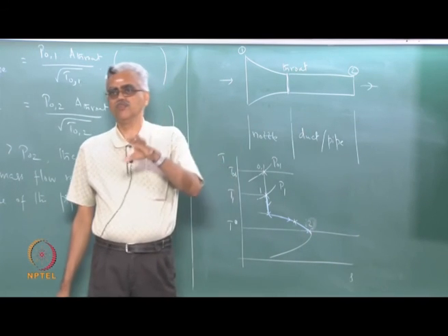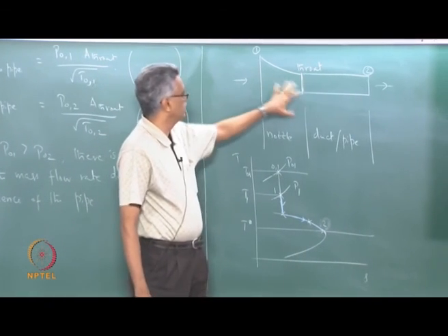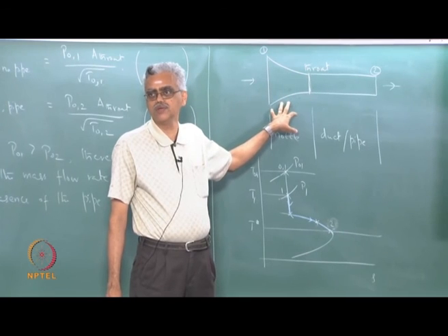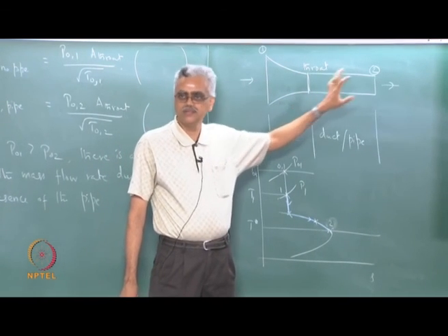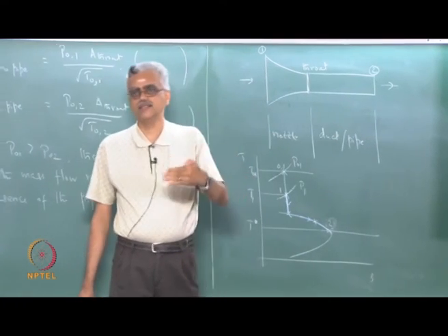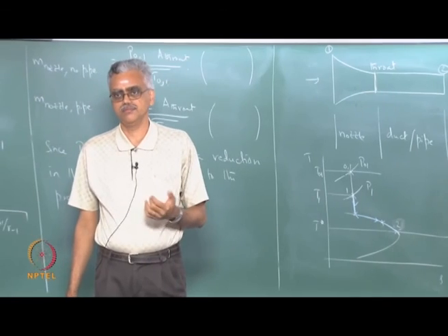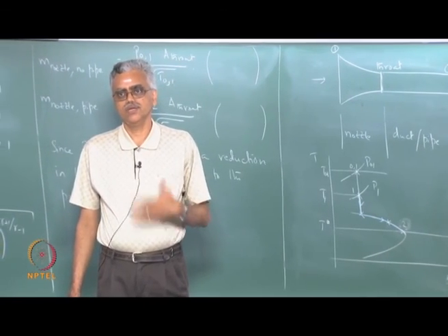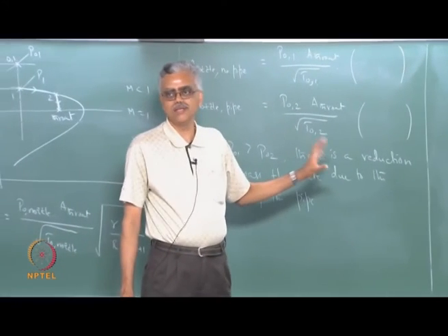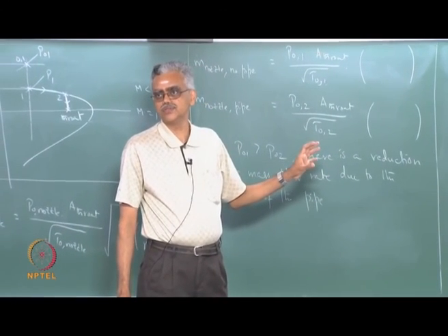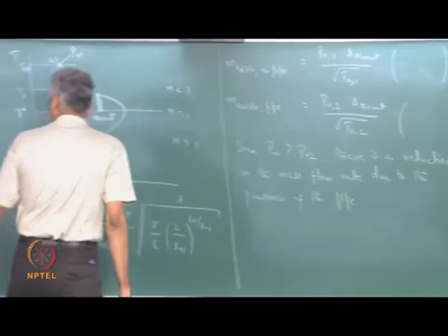So, you have a compressible flow equipment, let us say a test section or something else, you want a certain mass flow rate, so you design a nozzle to give you that Mach number and mass flow rate. Now, when you connect the pipe to it and take it to the test section, you realize that the mass flow rate is no longer the same and the Mach number is also no longer the same perhaps. Okay. So, that is a very important thing, that is why these problems are very important from practical situations. Okay. All right.